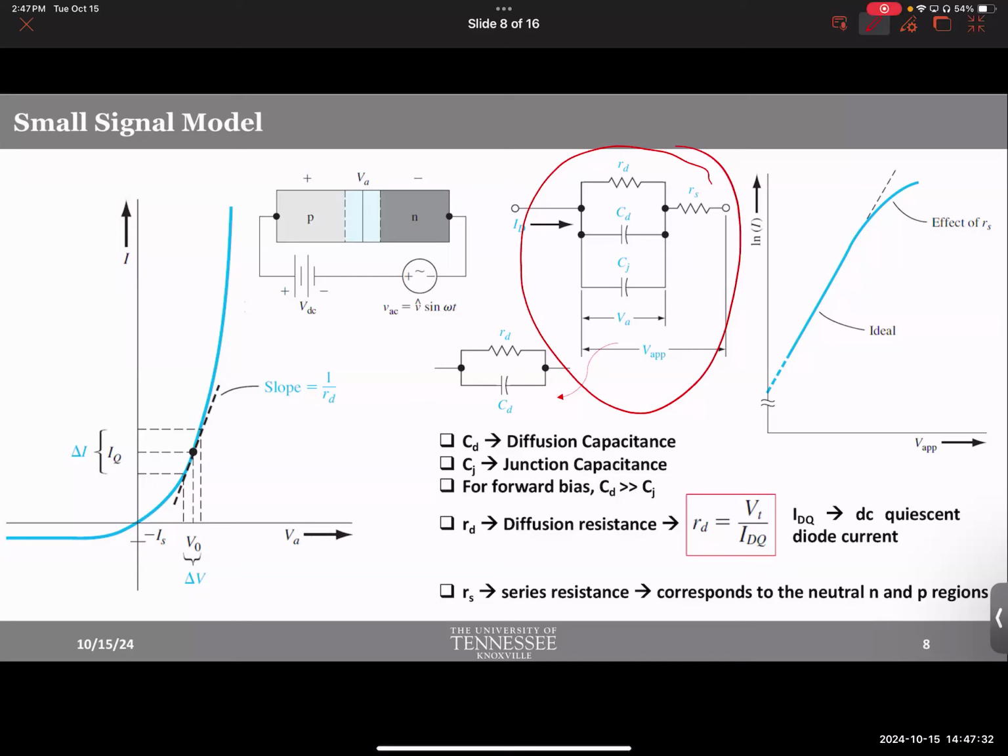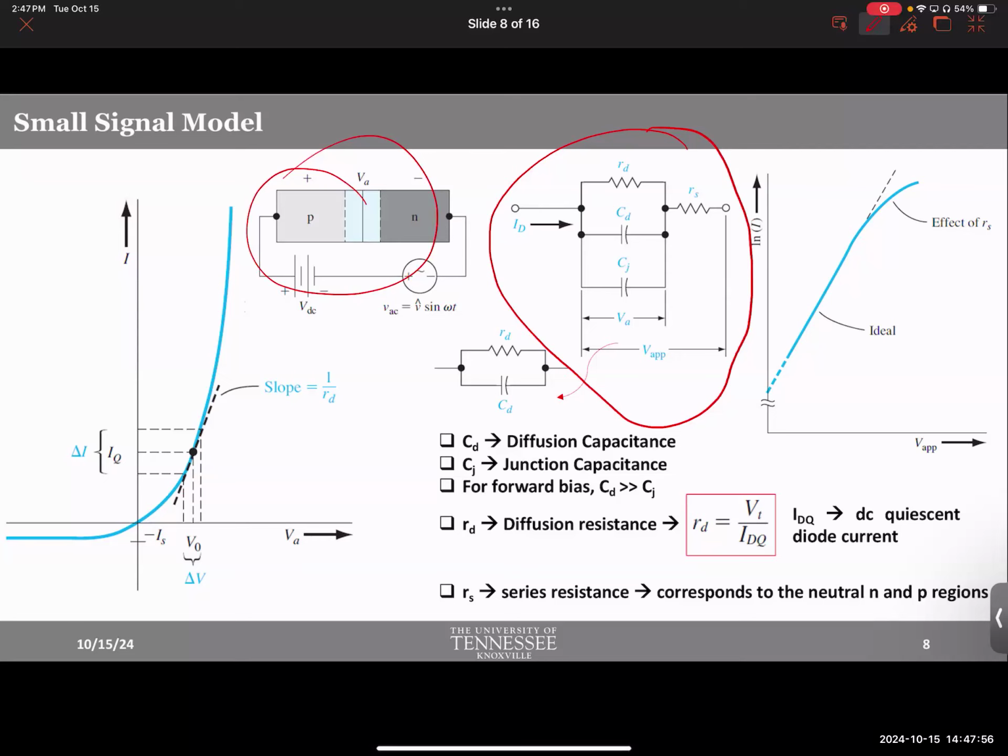And theoretically, you should be able to represent any electronic property with resistors, capacitors, inductors, because they are the fundamental components. That's the concept. At least that's the hope. You may not be able to figure out how exactly. So we often use some tricks and some approximations to do so. But theoretically, everything has inductance, capacitance, and resistance. And merging these three in a more complicated way, you could represent any complex phenomena. So this is one example. And obviously, as you can imagine, the easiest possible example of an equivalent circuit, because this is the easiest possible device, right? We try to replicate different phenomena within the device structure with either a capacitor or a resistor.